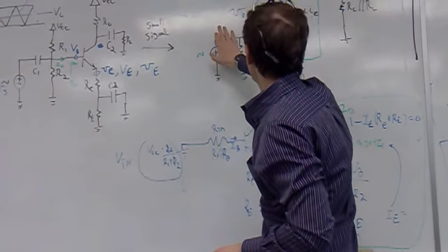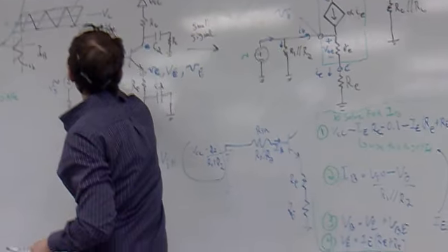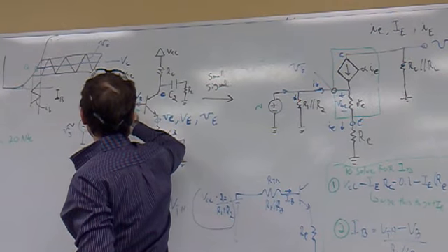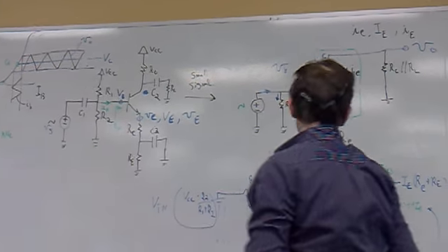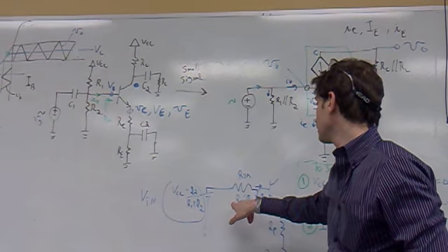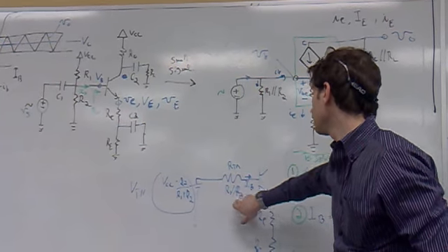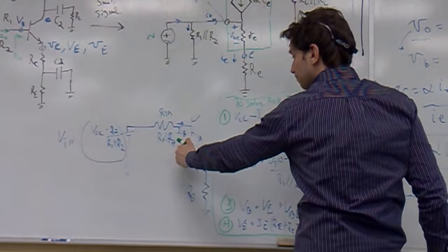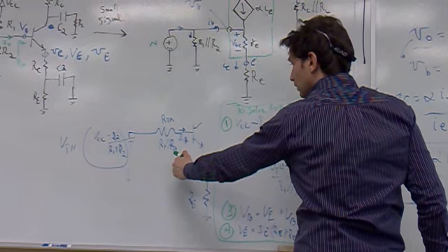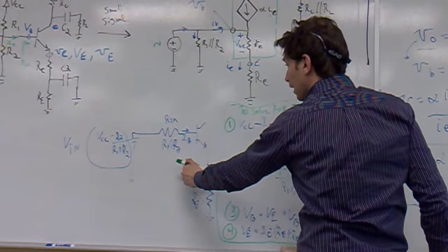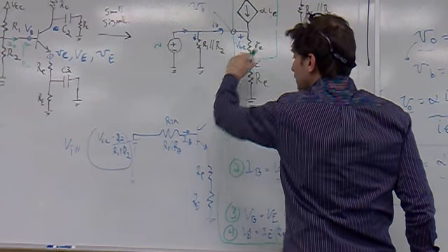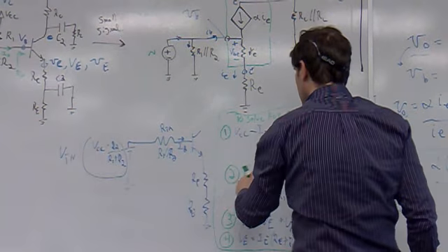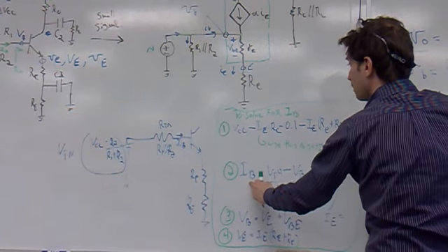All of my IB, this is locked off, right? All my IB has to come from here or from here, right? All of it. So you have the IB sucking through here, R1 parallel with R2. Then it's going to go through R capital E. Notice we don't care about R little e. We care about this R and this R, because the one inside we don't care about. Now it's DC. So, over R1, R2, so that's IB.